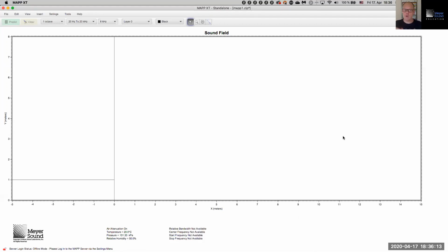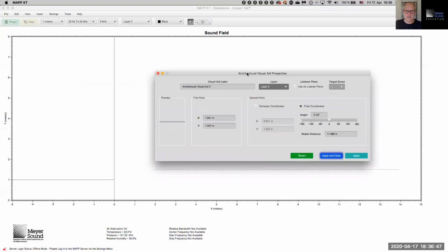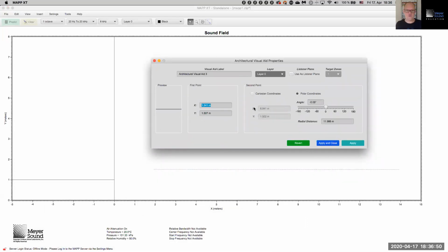Okay. Maybe it's also prudent to draw a line which represents the ears of the listeners at ear height. For ear height, I typically use 1.7 meters, and for all we know, today's audience might start at 2 meters distance. There are several ways we can do that. We can do it roughly by saying, okay, maybe this is where the audience lives, click and drag, and then I can polish it if I desire to do so. By selecting the line that I just drew, right-click, bringing up the menu, and going to edit the properties of that line, I can now position those values very specifically.